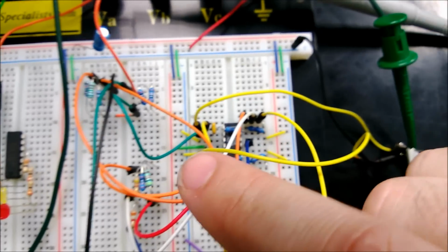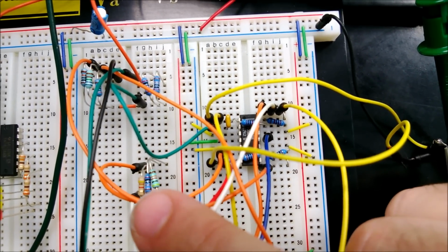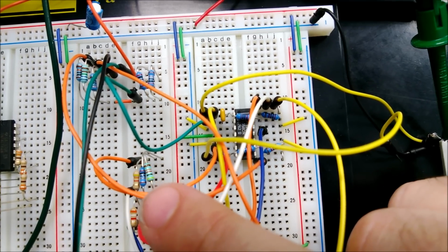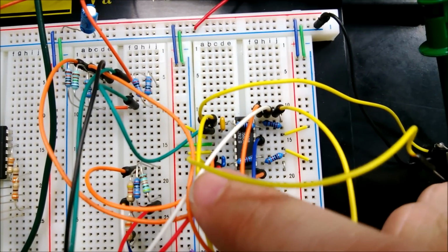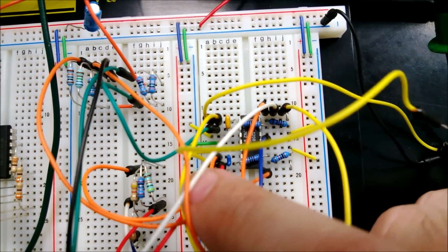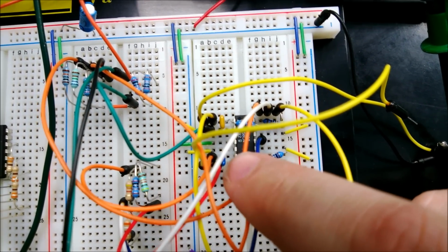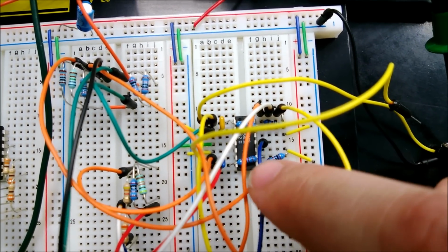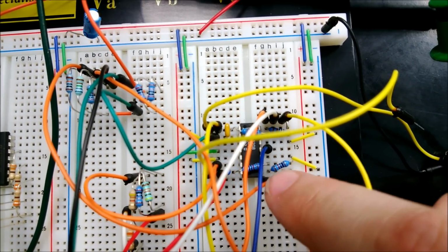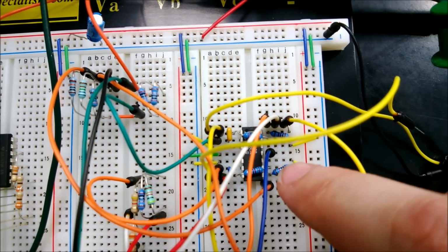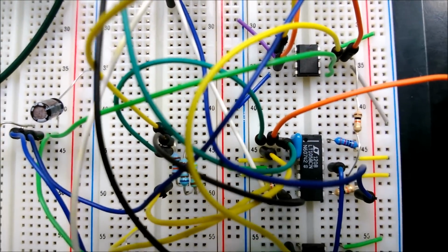We then move on to the y part, where we have our inputs of x squared, y, and minus 1, and those come in and get integrated over here with this capacitor. It's a little messy, sorry about that. That is our y output, which then jumps over and gets passed through an inverting amplifier with a gain of 1, so that we have our y and our minus y out here.